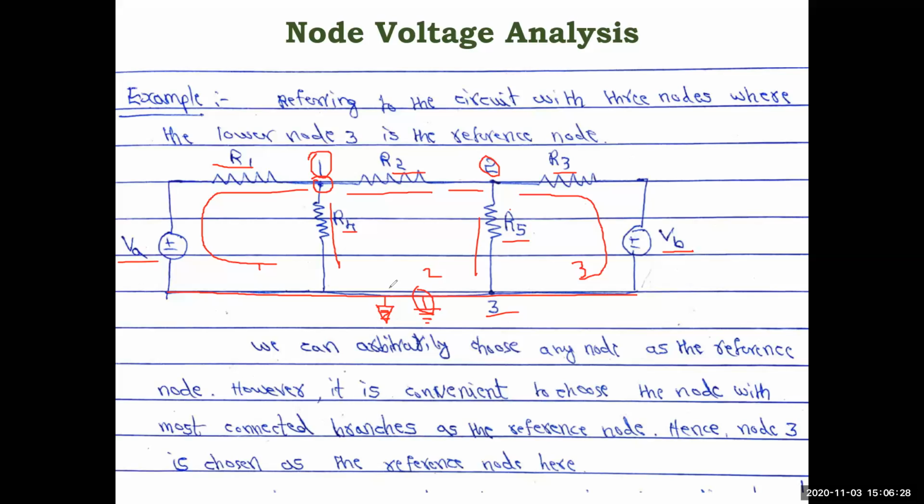And there are also some consequences. When you have to find a branch current, we can straight away go for mesh analysis, because finding the node voltage and then going for the branch current is a reverse process, right? In the same way, when you have to calculate the junction voltages, there is no need to go for mesh analysis and then calculate the voltage. It is again a big process. Instead, we can straight away use node analysis. So it depends on which parameters you have to calculate from the network. Based on that you will use either of these methods.